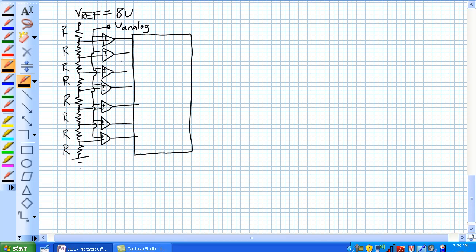Okay, so now all these outputs from the voltage comparators are being placed into a priority encoder. Remember from that 74-148 lab, the priority encoder, where the highest number pressed is the only one that's displayed. So that's the whole point of a priority encoder. And let's say we have, so that's 7, and then you don't really need a ground, a 0 volts one.